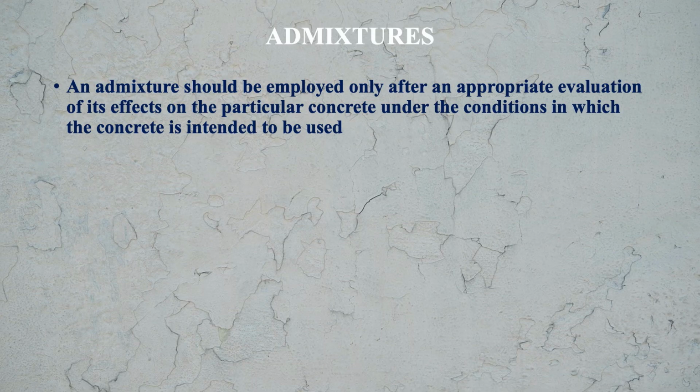And admixture should be employed only after an appropriate evaluation of its effects on the particular concrete under the conditions in which the concrete is intended to be used. It is not simply by recommendations of somebody or some guidelines that we use the admixtures. We have to properly evaluate the effect of admixtures on the concrete, in the conditions in which the concrete is being used.